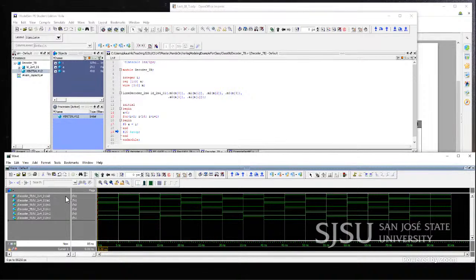So you see that as it was looping through the 1 to 16 values, your A0 is almost like a clock signal. It's regularly toggling between 0 and 1. And the A1 as well, it is toggling between 0 and 1 with a lower frequency, but they are repetitive signals because I am looping through the 16 values and assigning the last 2 bits onto A. So that's the significance.